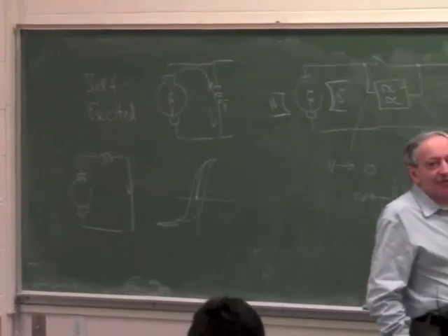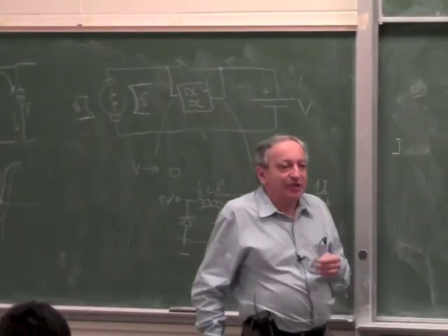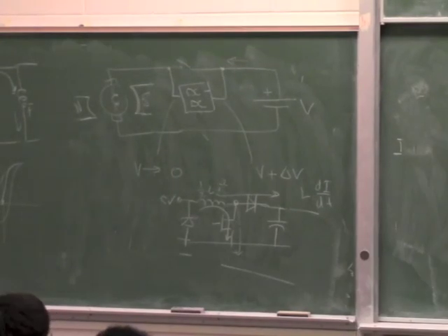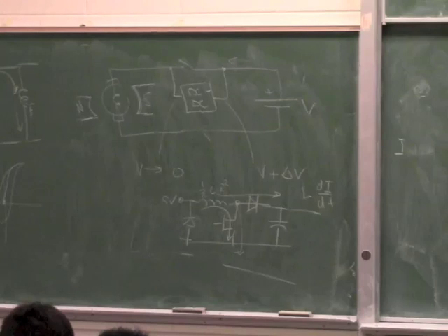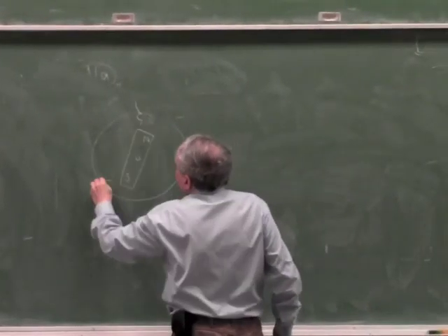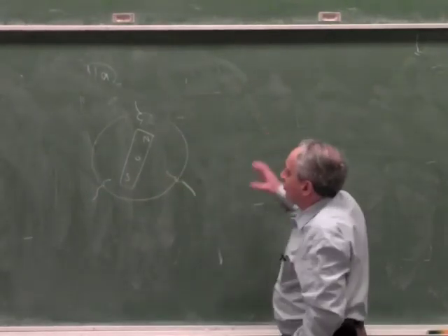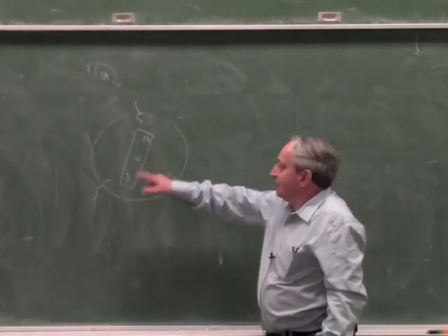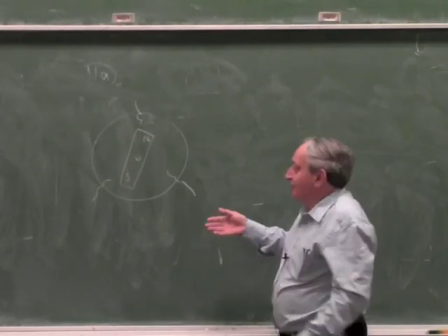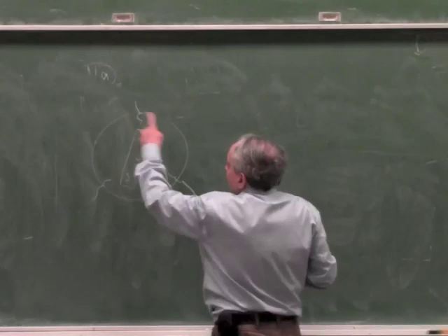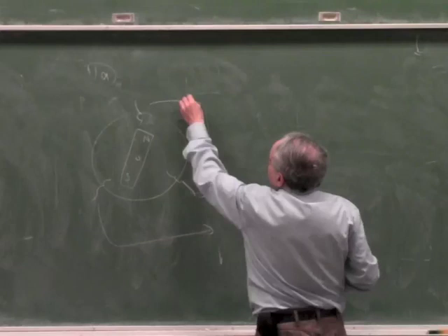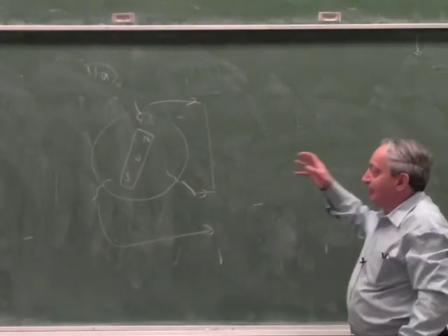It takes a little bit more thinking. How does it work in synchronous motors? In a truly synchronous motor, it's still easy to understand, because a truly synchronous motor, we said, has a magnet, N and S, and has coils. So if you don't feed power to the coils and the magnet is rotating, power will come out, because it's still a generator. You have a magnetic field rotating on coils, so 3 sine waves will come out of the 3 phases, and they look exactly like the sine wave used to drive the motor.